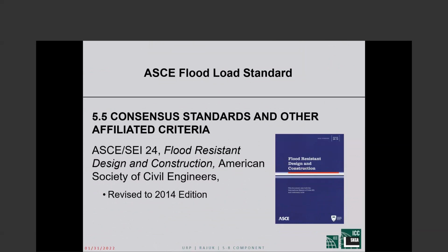In the US, the standard that is supposed to give you flood loads is ASCE 24, the standard that you see before you, Flood Resistant Design and Construction. The 2014 edition is the second edition of the standard. The first edition was about 10 years earlier, 2004 or 05 kind of time frame.